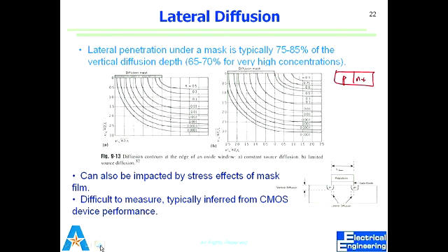Becomes ash. So you said ion implantation is faster than diffusion, but in ion implantation you need to do annealing, right? You have to do what you call annealing in diffusion as well. You have to do an activation run in diffusion as well. So what you're comparing is only the time of the dopants entering. Not just the time it takes to get the dopant into the substrate, but their initial profile as well.